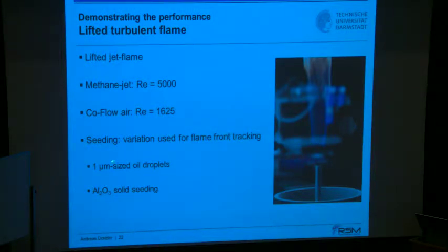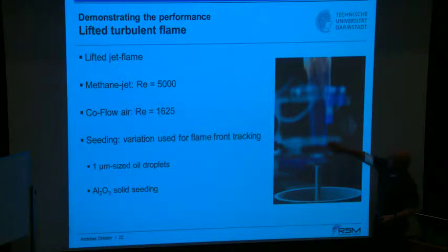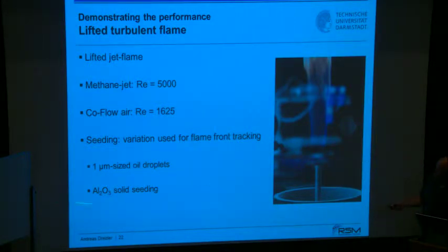In terms of oil droplets, they are vanishing, they're burning, such that you have a very high contrast, with no seeding and no Mie scattering inside the flame or inside areas where it's hot, and outside you have Mie scattering. Using chemically inert particles, for example alumina oxide, it would be just a density jump.